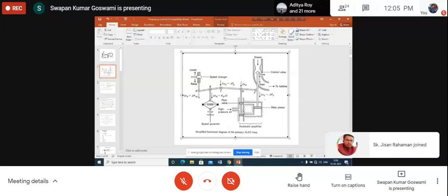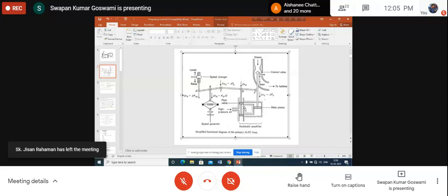That means there will be no shifting of oil from one cylinder to another, or from the oil pump to the cylinder. There will be no change in the oil movement, but the pressure will be kept fixed by the oil pump. Oil is at its predetermined value, so there is no oil movement. The opening of the steam valve is at a certain position. So E is fixed, which means D also will be fixed at its previous value. C also will be fixed at its previous value, and since there is no change here, you cannot change C directly now.